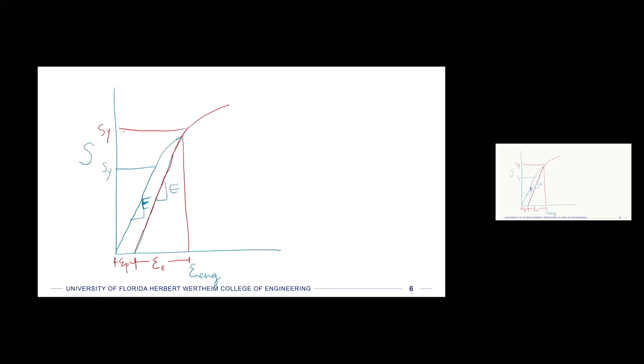Okay, so how can we describe this increase in our yield stress with the strain that's been induced? I'll draw an arrow right there. What we can do is try to fit this to some sort of a curve that describes it. We measure engineering stress and engineering strain. If we transform it to true stress and strain, I'm going to draw that plot next to it right here, and we transform it from maybe a linear scale to a log scale.